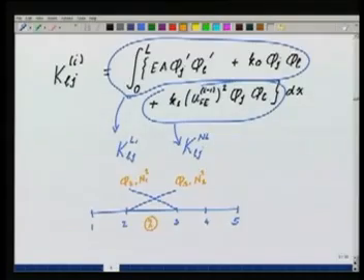So, when I am doing this integration, I am going to construct these element matrices first, and by summing them together using our assembly procedure exactly the same way as we had done for the linear problem, we will get the nonlinear equation. So for element 2, let us say I now want to get the element matrices.